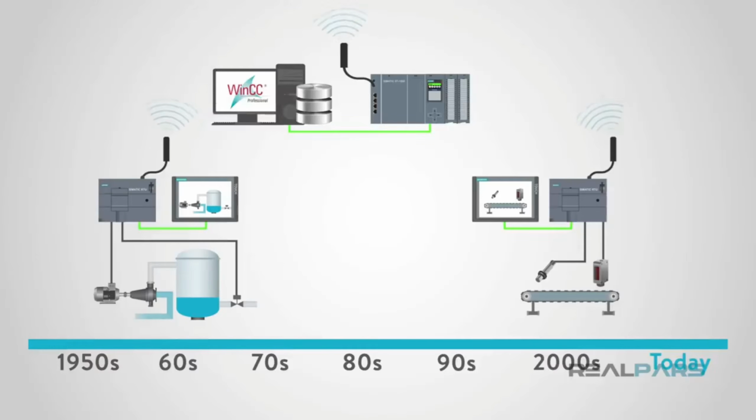Essentially, SCADA is a collection of hardware and software components. This collection of components begins with real-time data collected from plant floor devices, such as pumps, valves, and transmitters. These components don't have to be from a particular vendor. They just need to have a communication protocol that the processor can utilize.